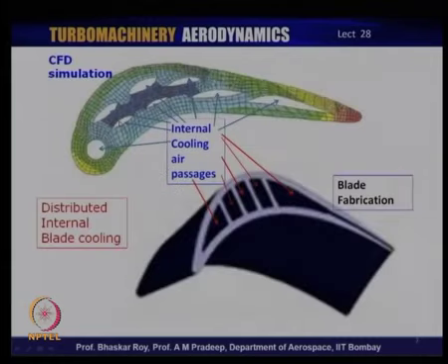So, that is what we were discussing, that the amount of coolant to be used here, over here, over here, and then near the trailing edge over here would indeed vary substantially depending on the blade shape, depending on the temperature at which it is operating, and of course, depending on the cooling air that is made available. Now, all this needs to be calculated very accurately. This accurate calculation is where engineering and heat transfer science comes in very strongly.